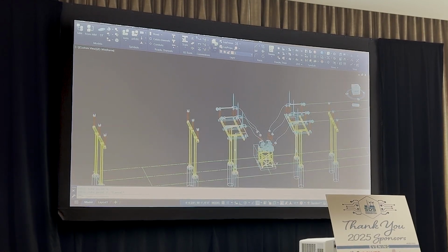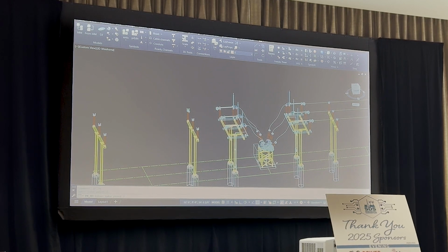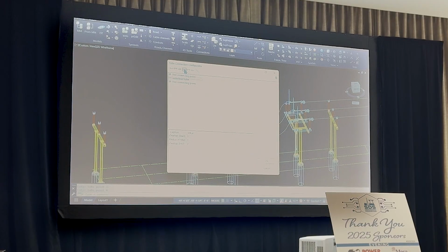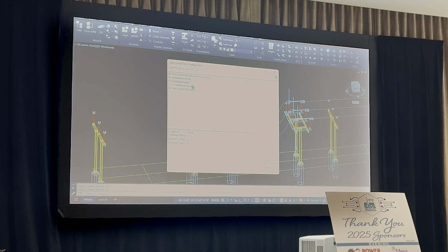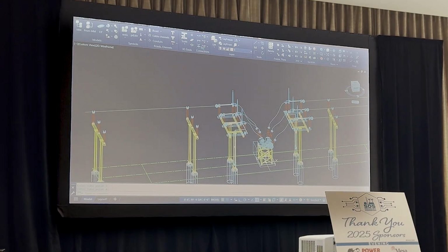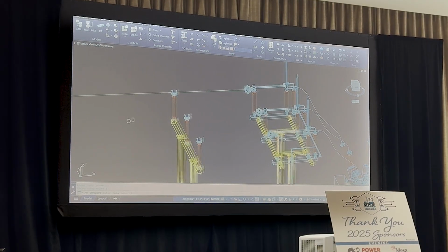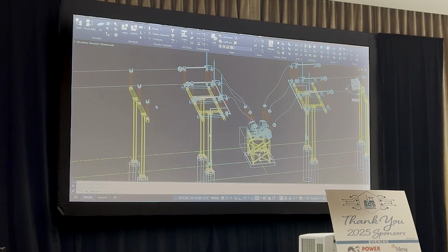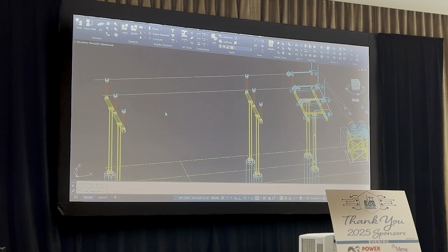This other side I'm going to run different. So this one I'm just going to go take my supports. This one I'm going to do where it stays undefined with undefined wire. And I'm going to put a fillet fitting on either end that's undefined. So what these undefined things do, they show up in a parts list and actually get counted. You just don't know what they are yet. And then they'll display here a little bit. Overlap, 36. Again, I could copy that over to here, here, and then here to here to here.